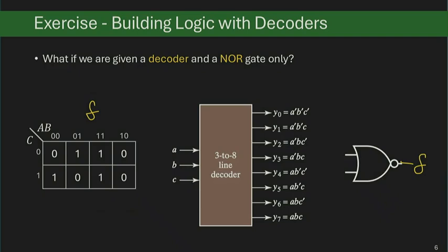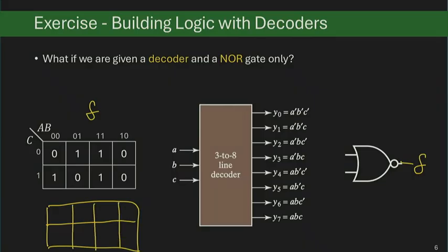What do you mean by flipping stuff in the K-map? You could flip the numbers. So you're saying that we create the complement K-map. So do you want to flip all the numbers? Yeah. OK. So I'll create a complement K-map: 1, 0, 0, 1, 0, 0, 1, 1. This is really the K-map for F complement. All right. And then what do you do with this flipped K-map?